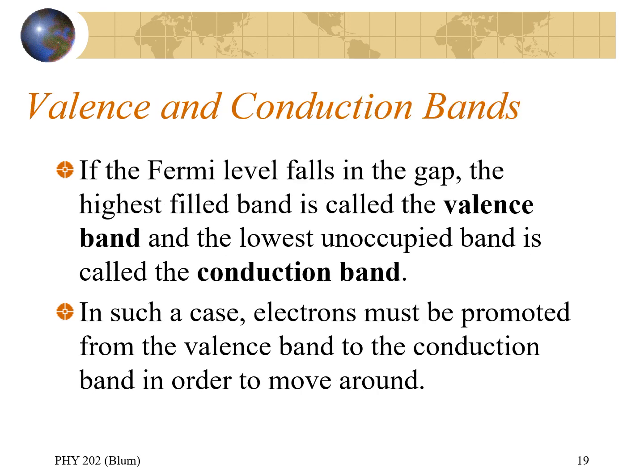So we have many energy levels forming bands, and then we have gaps between the bands, and the Fermi level was the highest occupied level. If the Fermi level falls at a gap, then we talk about the level below it being filled and called the valence band, and the level above it being unoccupied and known as the conduction band. And electrons will have to go from the valence band up into the conduction band, sort of getting enough energy to leap over the gap in order for there to be a current.